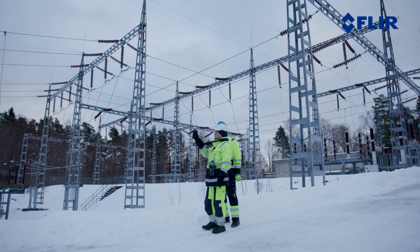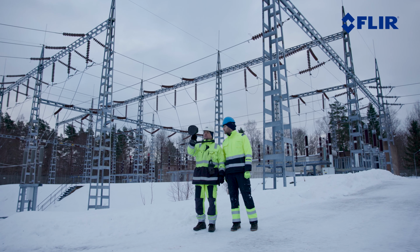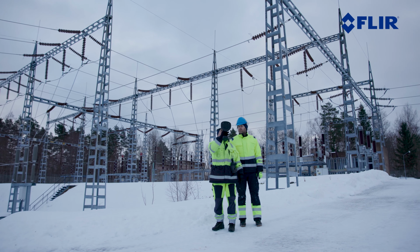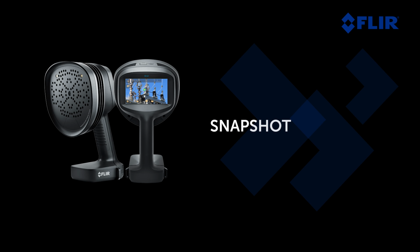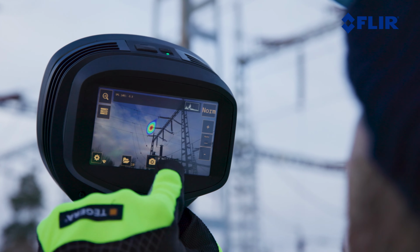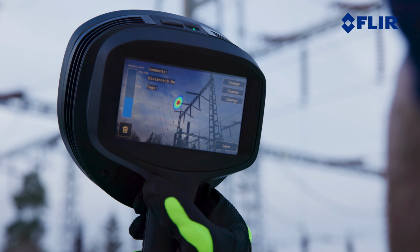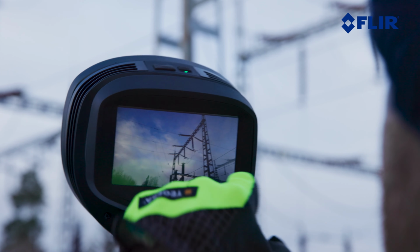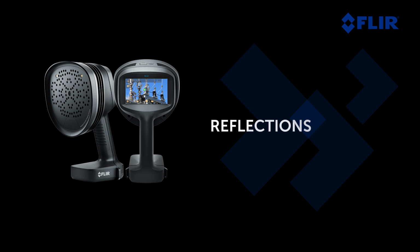When inspecting power facilities filled with electrically charged equipment, being able to detect PDs without contact and from a safe distance is key. With the SI2, you can now extend your detection range to up to 200 meters. To take a snapshot, press the snapshot icon and name it. For the most accurate analysis results, enter the approximate distance, voltage, and component where the PD was detected.